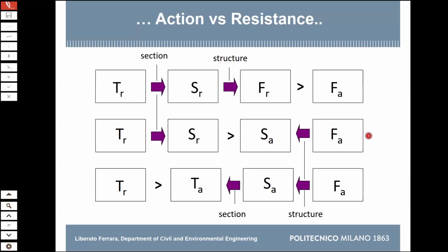And then we say, for example, we have a frame structure and we hypothesize that this maximum moment capacity is achieved in a number of cross-sections just equal to your degrees of hyperstatic plus 1. Because if you have a structure which is 1 times hyperstatic, if you form 2 hinges, it becomes a mechanism and it fails. So you can calculate through the theory of plasticity the load which corresponds to this mechanism, and you check that this load is larger than the design load.